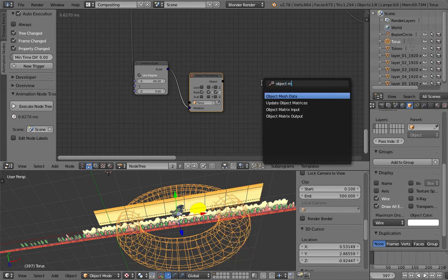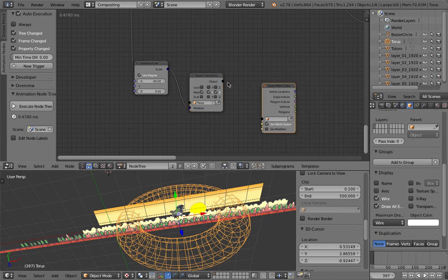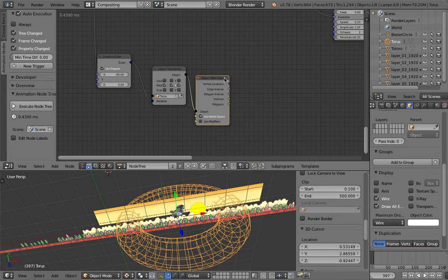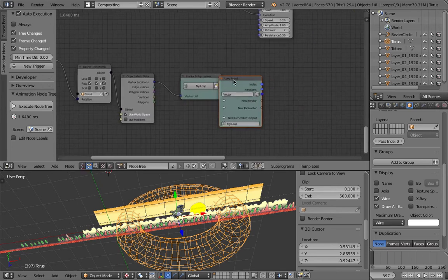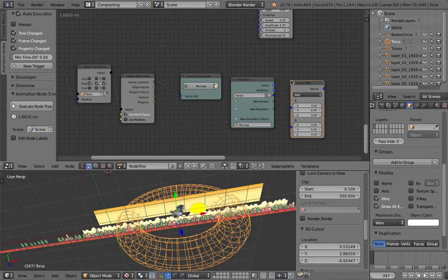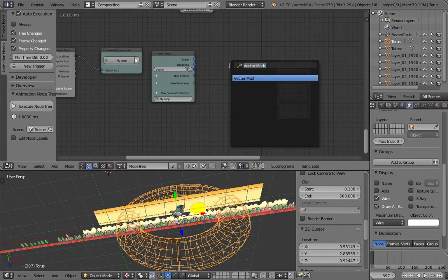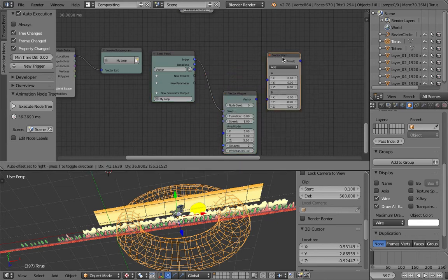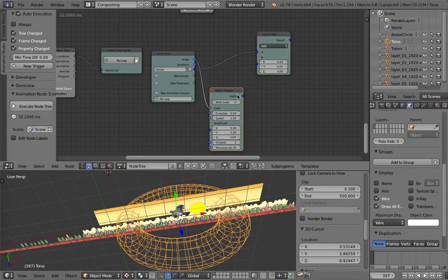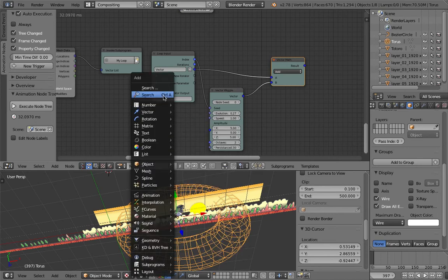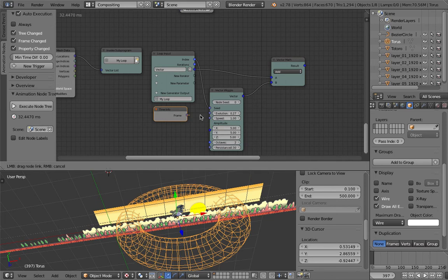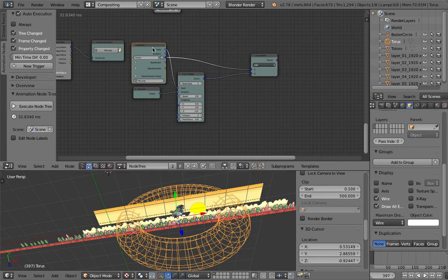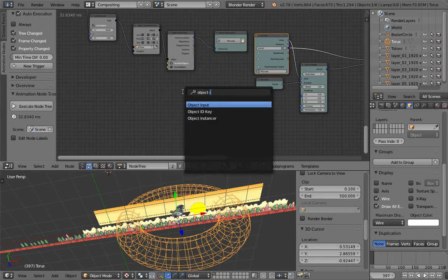So object mesh data, get our objects and get the vector locations, and then now loop through vertex location, and then use vector math, randomize the position using wiggle noise, vector wiggle, plug the index into the seed, and this guy get the original vector, and then use a frame number here. And use this position for our object instances. Object instancer.